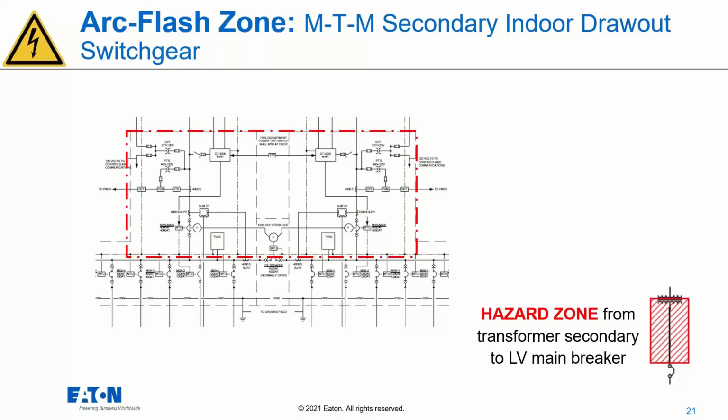And before I go into the values that we're going to see, the primary vacuum recloser in an always-on solution like this must be coordinated with the transformer inrush. So if we look at transformer inrush and damage curve, that damage curve is when too much energy is going through it, that it will damage the transformer. And then the inrush curve represents the amount of current that will be pulled into the transformer during startup.